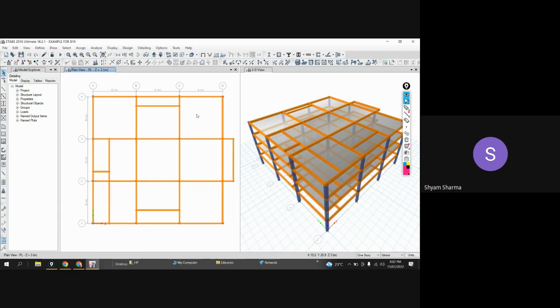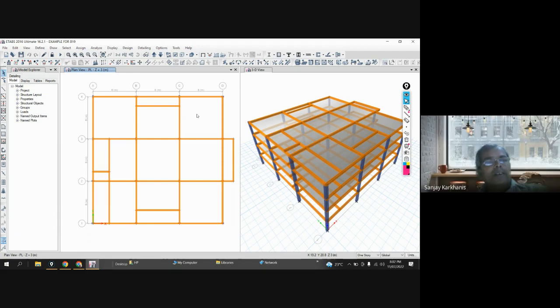And any other dead load which is not an integral part of the element, that is, which is not self weight, I will create in a different primary load case, and that's why I'm saying SDL, superimposed dead load. So that is the difference. Actually, both are dead loads, both are static loads. For our convenience, we are saying that self weight is different and SDL is different.